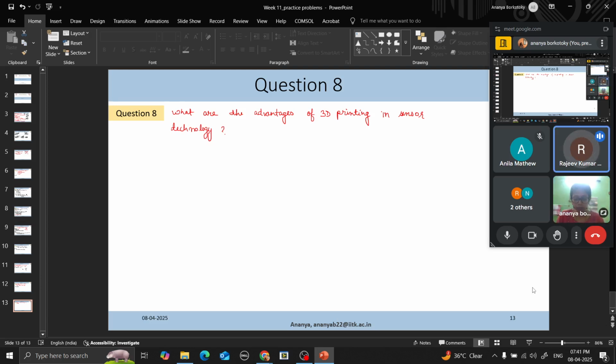It can create complex shapes. Yes. So we can make the design using some tool, and we can just go for 3D printing. But what can be the other advantages, and what do you think are the disadvantages in case of 3D printing? Strength is not too much, strength is less. And many times we cannot use the same component as a structural component. Yes. So we are limited by the material with which we are printing.